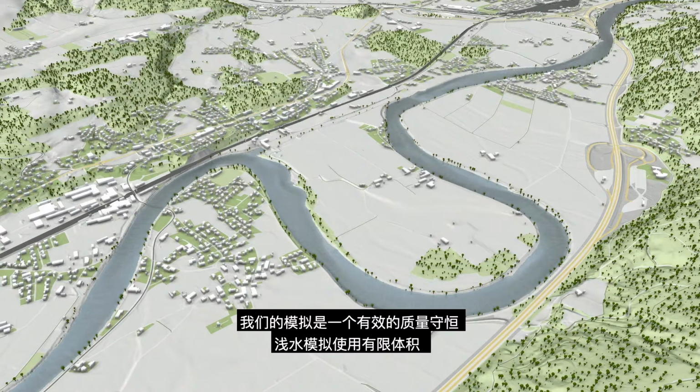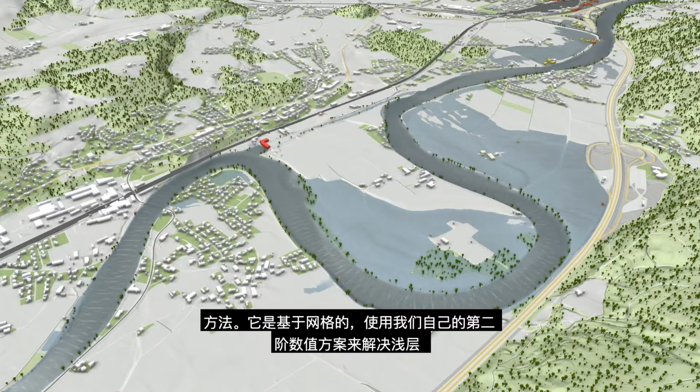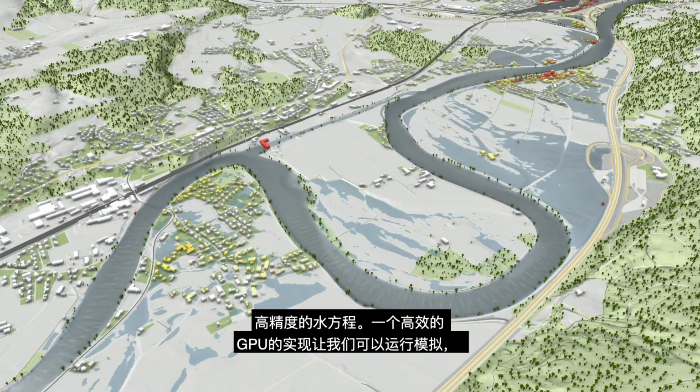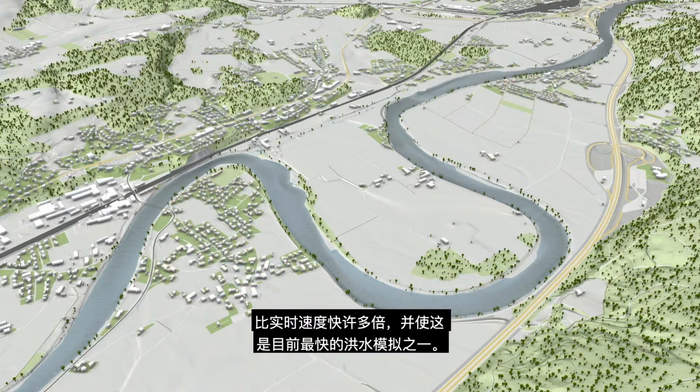Our simulation is a validated, mass-conserving shallow water simulation using the finite volume method. It is grid-based and uses our own second-order numerical scheme to solve the shallow water equations with high accuracy. An efficient GPU implementation allows us to run simulations many times faster than real-time and makes this one of the fastest flood simulations available.